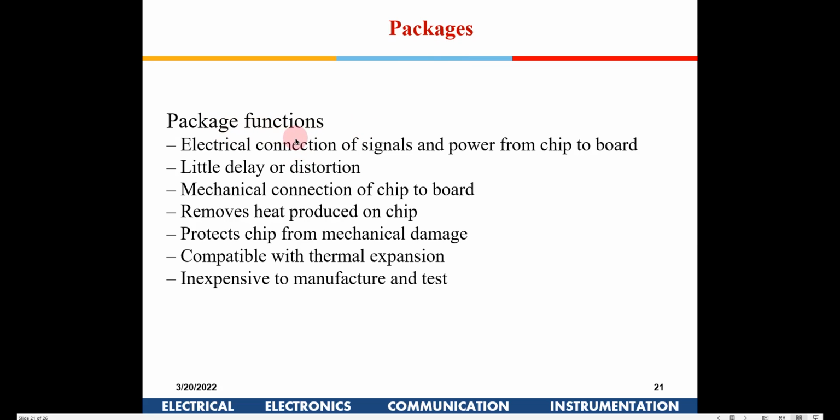Okay, so now what is the function of packages? Electrical connection of signals and power from the chip to the PCB board, with little delay or distortion. A mechanical connection of the chip to the board. Removing heat: whatever heat is generated in your circuits needs to be dissipated. And protection from mechanical damage to the actual silicon chip. It should be compatible, because of heat these chips will expand a little bit, so that needs to be taken care of, and it should not be very costly. So these are some of the functions of a package.